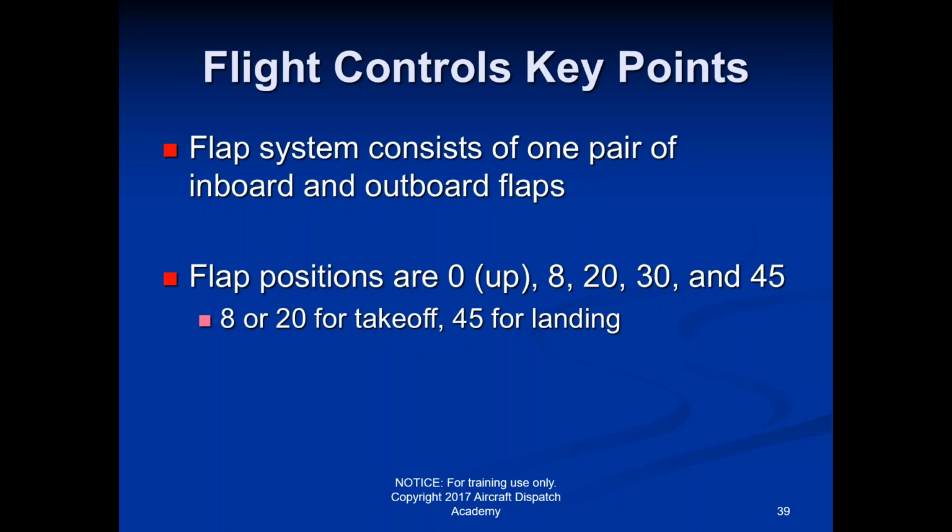However, the downside of having the flaps at 20 is that it decreases the overall performance, so it decreases your takeoff weight capability. In some cases it doesn't make an actual effect, but generally speaking, flaps 20 for takeoff will be a worse takeoff weight penalty, even though it's allowing you to take off quicker. The ideal situation to use flaps 20 is if you were taking off on a relatively short runway. The shorter the runway, the quicker you need to get off the ground, obviously. Just basic math on that, right?